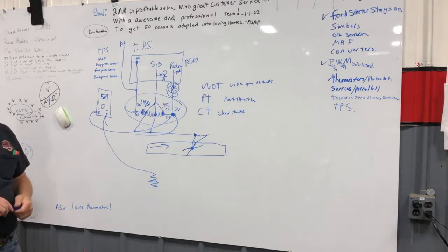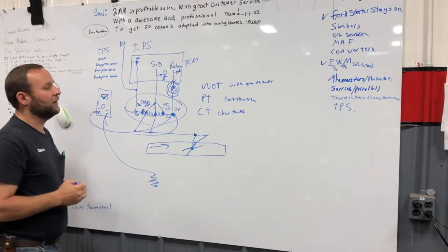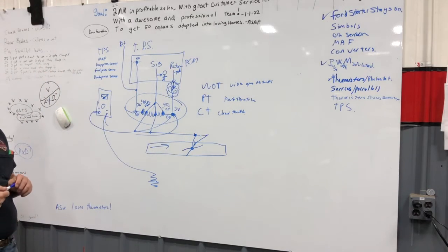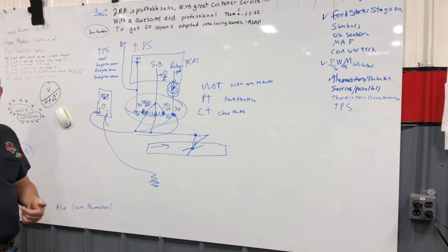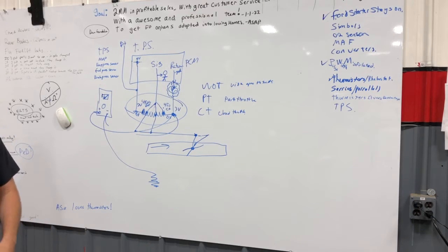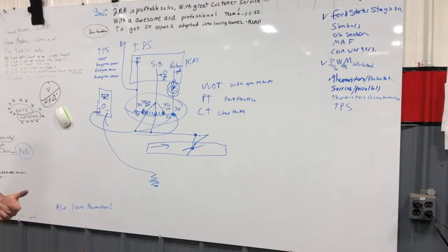Between there and wherever. I mean, it could be right here at the computer, you could have green stuff coming out. So do you then check that wire in sections to find out what parts? I like to split stuff, yeah. I'm gonna start pulling on a couple wires and just looking at the wire harness, and see if you got anything scrubbing, see if you got nasty stuff. But I mean, this doesn't happen very often.